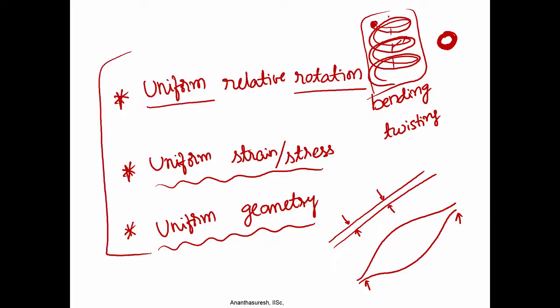Okay. That will be the ideal distributed compliant mechanism, and this is where, to achieve what we have listed here, a lot more work is needed, and that is an open problem in compliant mechanism synthesis. So, the last lecture and this lecture tell us why these one node hinges occur, and it is actually a problem in any of the formulations that we have discussed, 5 different formulations. So, we have discussed 2 different formulations, one in detail, the other one by Wang, Lazarov and Sigmund. We just gave a reference, you can look that up, how they used image processing, erosion and dilation concepts to get something that is distributed compliant.